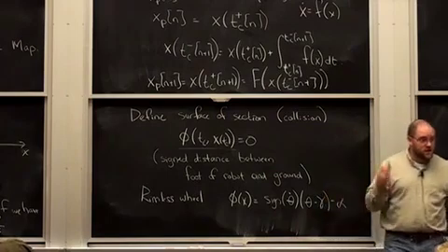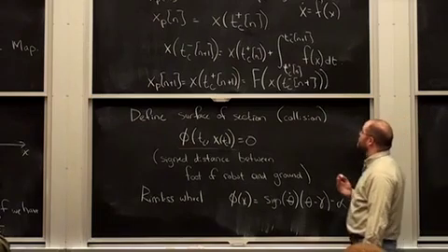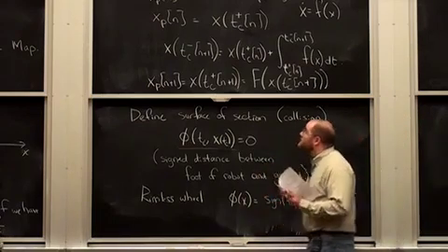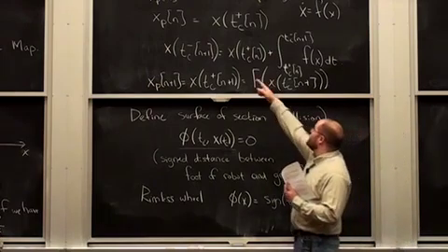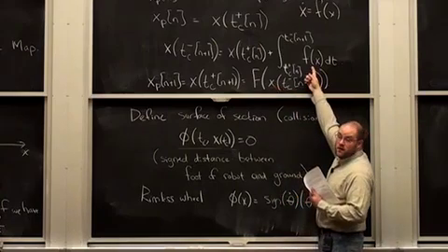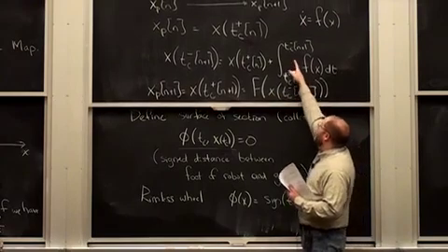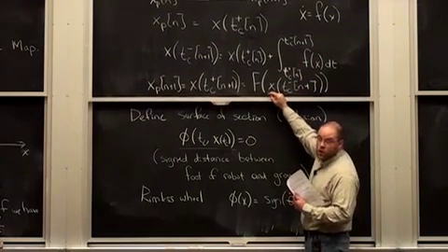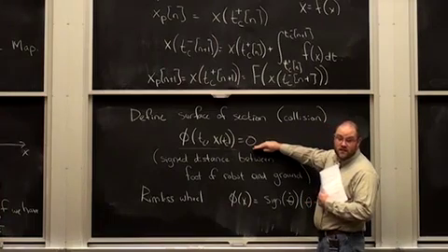Okay, so this is a sufficient recipe now for simulating the Poincare map, right? If I want to just evaluate in the simulation with the Poincare map, someone says I'm at state xp on the nth Poincare map. I'm going to turn that into my continuous time thing. I'm going to integrate forward my dynamics just like we always do, but I'm going to stop at a particular time, t c minus, which is defined as the time when it causes phi to equal 0.